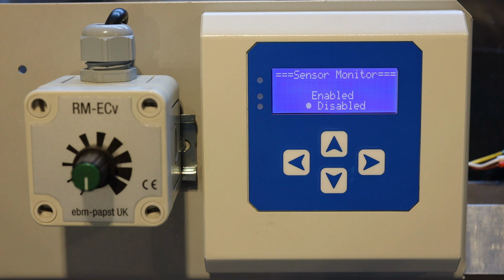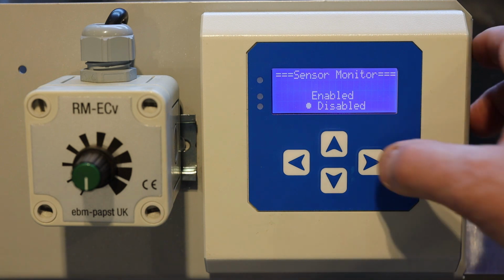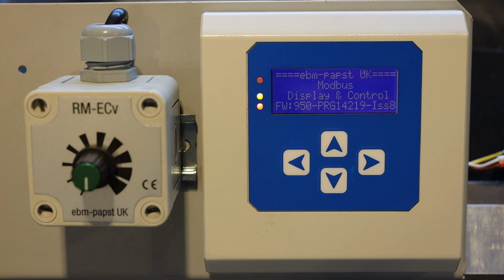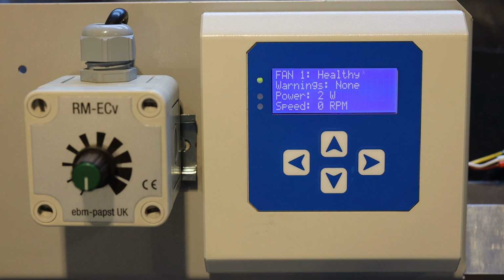At this point, if a pressure transducer has been installed at the control input of the MDC or at one of the fans in the array, the option Enabled should be chosen. In this case, we will not configure the MDC controller to read from a pressure transducer. Choose Operation Mode Modbus, after which the controller will perform a reset. After the reset, the controller will enter monitor mode, waiting for a command to be received at its server terminals.